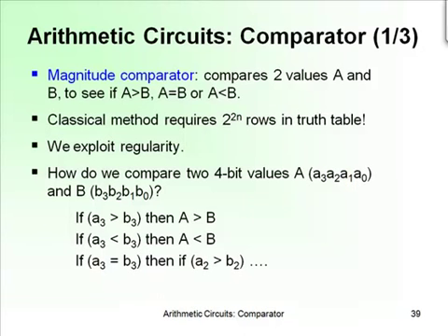How would you compare whether a number A is greater than B? The easy way to think about that is the most significant bits. If you have 4 bits and bit 3 is 1 in one number and 0 in the other, you know that number is greater. So essentially we start looking from left to right and wait until we find that discrepancy. If it goes all the way through, we know they're equal, and we can negate that to determine whether or not it's less than.